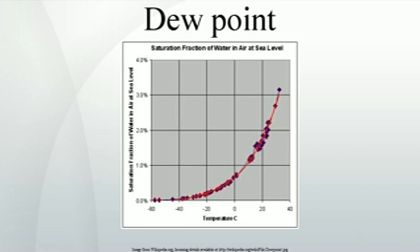OSHA recommends indoor air be maintained at 20 to 24.5 °C (68.0 to 76.1 °F), with a 20 to 60% relative humidity, and a dew point of 4.5 to 15.5 °C (23.9 to 59.9 °F). Lower dew points, less than 10 °C (50 °F), correlate with lower ambient temperatures, and the body requires less cooling. A lower dew point can go along with a high temperature only at extremely low relative humidity (see graph below), allowing for relatively effective cooling.